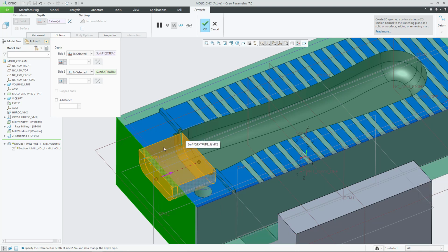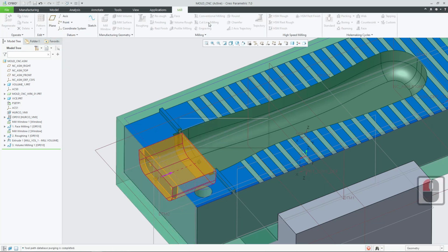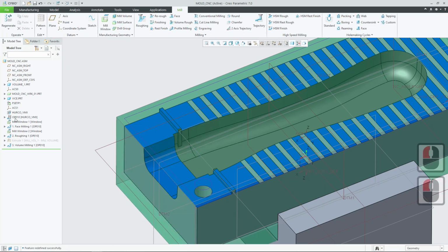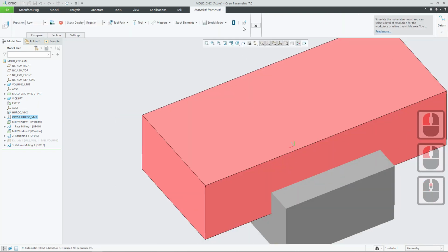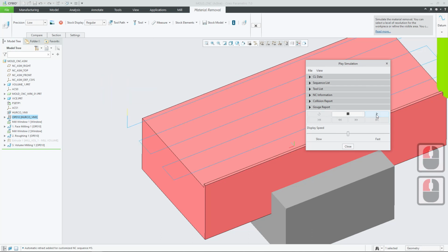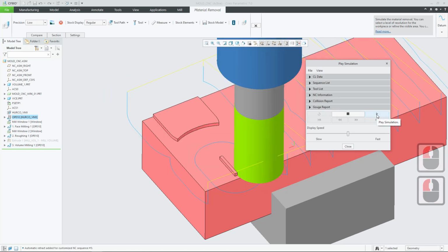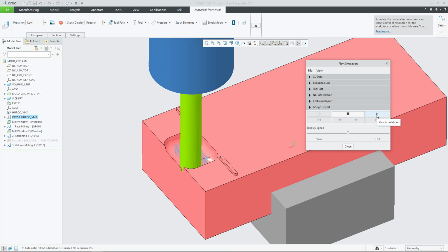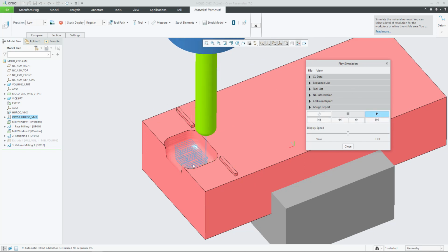So there's our sketch in the middle. We initially extruded over there. We've now said we want to extrude in the opposite direction by a certain amount. So if we click on OK now, and then try simulating all our steps again, let's see what we achieve. So I'm going to leave the stop at sequence switched off this time, because I just want to run through very quickly to the end of this whole set of machining sequences. So yeah, that's slightly better.